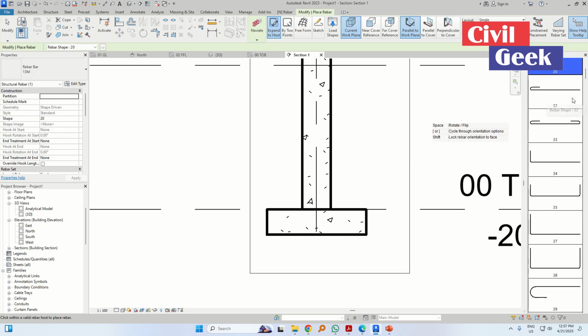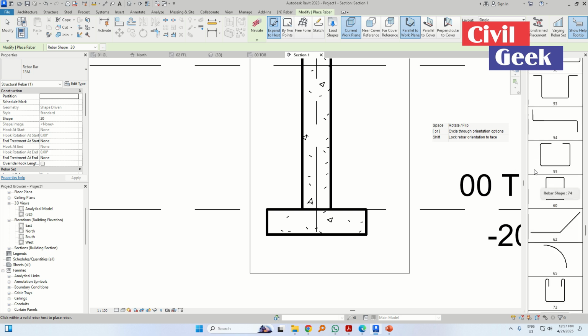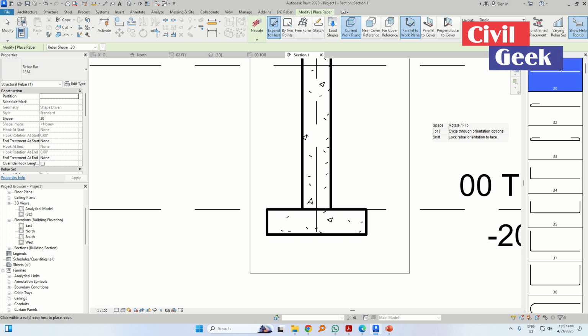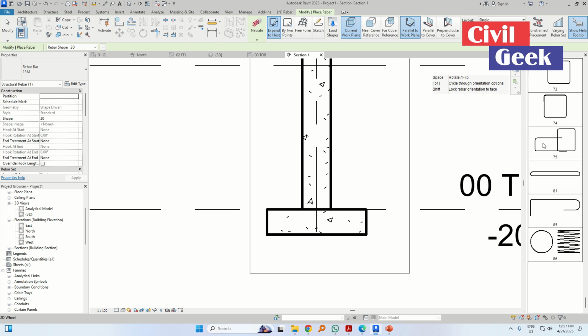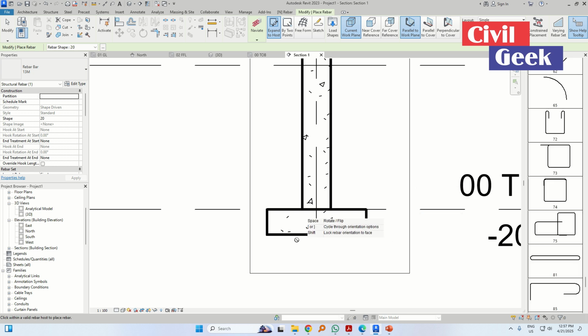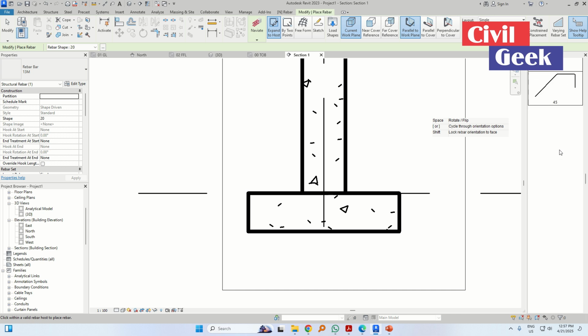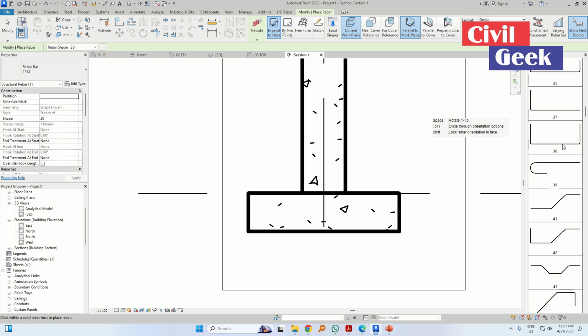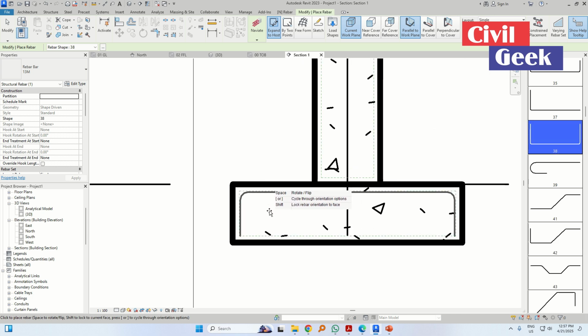As you can see, this is the South African rebar that we've been using. You know this by the shape code 20. That one is just a straight line. The ones normally used in the British standard that are very common, the 001 is the straight bar. Now I'm going to be selecting the actual rebar that I want. It's 38. Let me go to this one. Once I do that, you can see the rebar has been placed here.